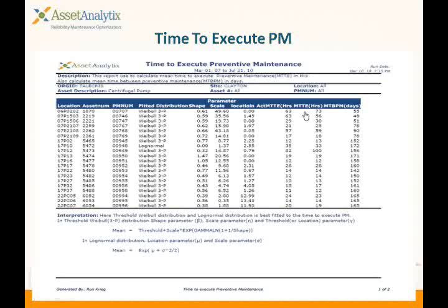There are many different KPIs that can be devised depending on what maturity level the PM program itself is at. For example, if you are at an initial stage, the highest priority might be only schedule compliance: if we have scheduled some PM, are we able to finish it in time? Or we can devise another KPI related to that: how many backlog PMs do you have? Out of total PMs, what percentage are backlog PMs?